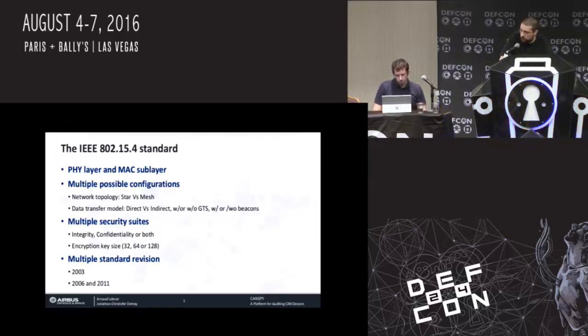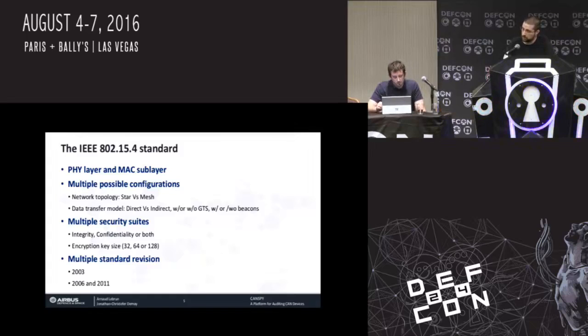You have really a lot of possible configurations with 15.4. For example, you can set up the network topology as a mesh network, where every end device can communicate with each other, or as a star network, where end devices must only send information to coordinators.